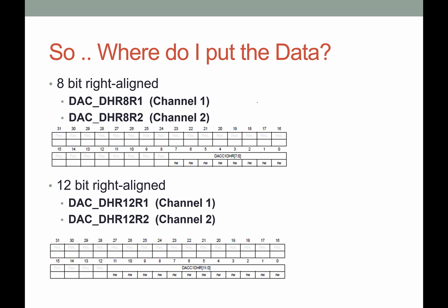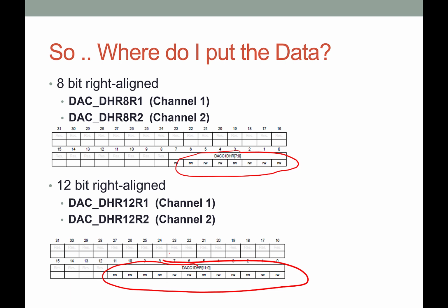It may be done the other way if there's some old system that was storing something in a different format. But for us, I think it's easier to do it as right-aligned. If it's 8-bit, there you see that. If it's 12-bit, there you see that. And the data holding registers will tell you how that data is stored.